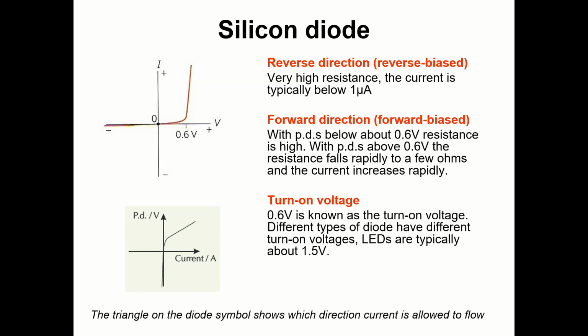And the knee or turn on or switch on voltage used to be a given that it was 0.6, but most of the time these days they say in the question what the voltage is, the switch on or knee or turn on voltage, in modern questions anyway. Worth talking about the reverse direction there being 0 in the exam, but probably a dark current flowing. Yeah, depends how much detail you want to go into really there before you go into electronics too deeply.